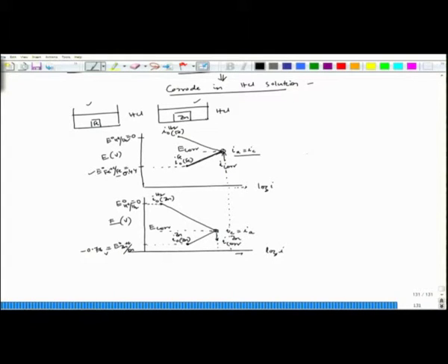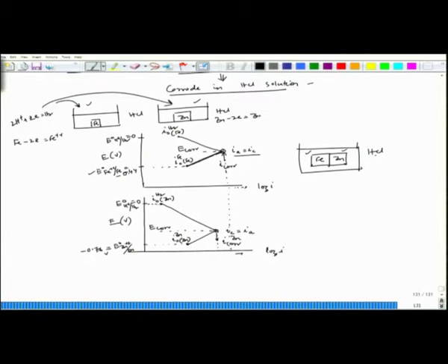Now, we have to join them. So, now this is iron, this is zinc. Now, we are putting it in HCl of the same concentration. What happens? In the separate case, this is active, this is also active, and the cathodic reaction here is H2, and a similar cathodic reaction is happening here. So, both the cathodic reactions are here, and here the anodic reaction is zinc going to Zn2+.